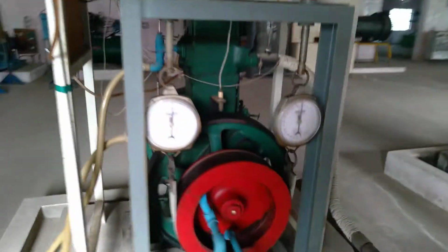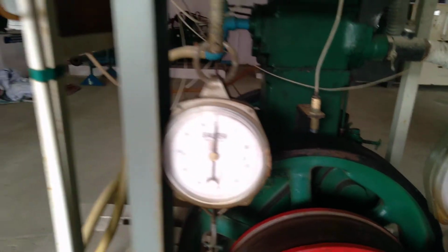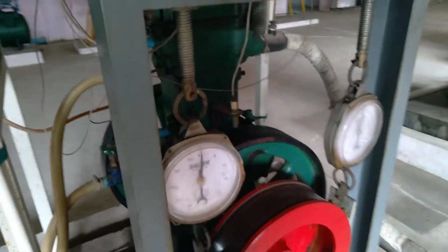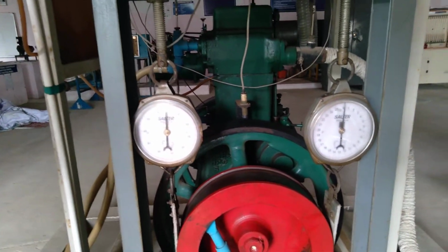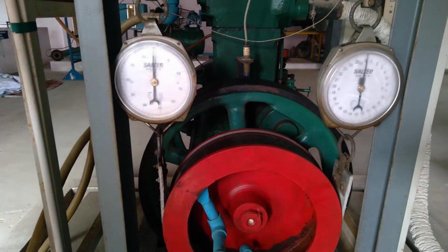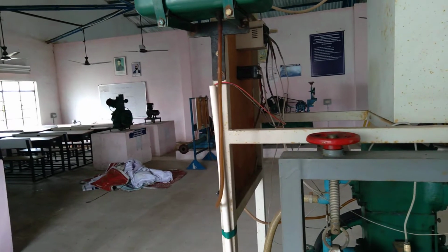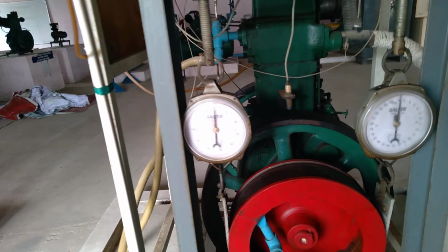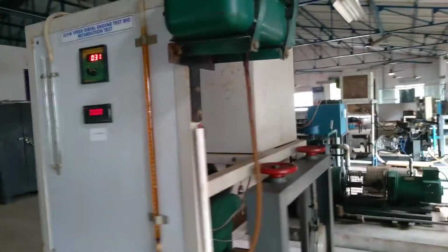Next we are going to start the engine and note down the following readings. We are going to maintain 4 loads. First we run the engine without adding load. By adding load, we are going to find out the drop in speed. We are going to measure how fast it is running, the time taken for 5 ml of fuel consumption, the exhaust gas temperature, the water outlet temperature, and the manometer initial head to final head.